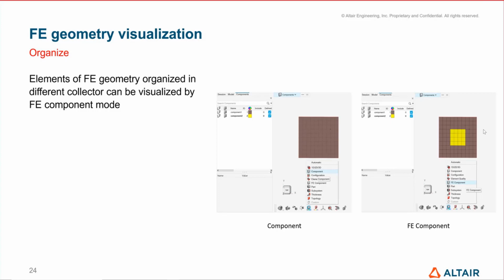One thing I would like to highlight: once you move FE geometry elements from the surface component to a new component, the new component, which has nothing but the element visualization, will have no effect. The CAD icon or the FE icon will not have any effect because the geometry is not in it. So the switching on the surface or the elements will happen only from the component where the surface sits.